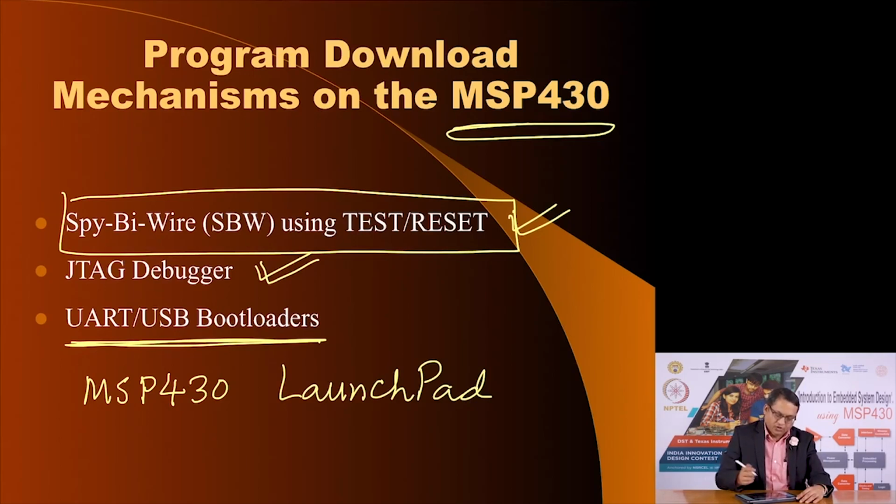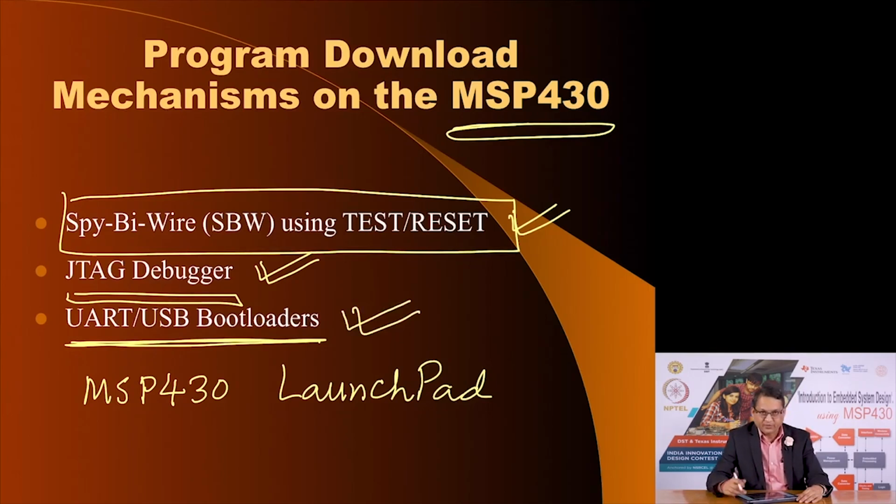If you choose to have an external debugger, it would require more pins to be connected, and the G2553 has access to those pins, but once you do that, you may not be able to use those pins for connecting to your peripherals. And as I mentioned, the third method is the USB UART based bootloader, which I am going to explain in a little bit more detail compared to what I discussed in an earlier lecture here.